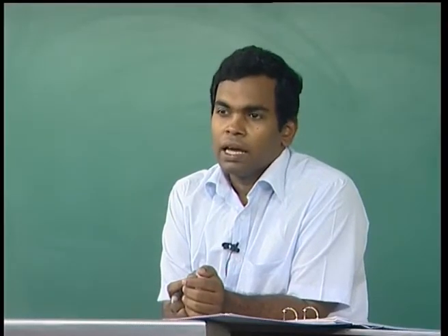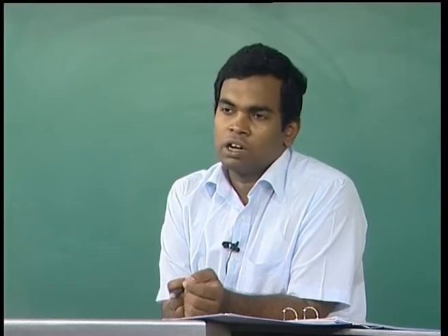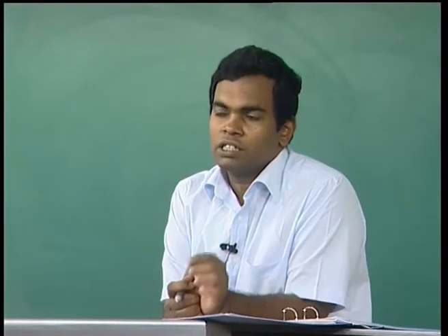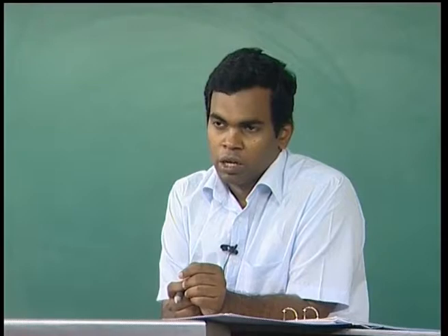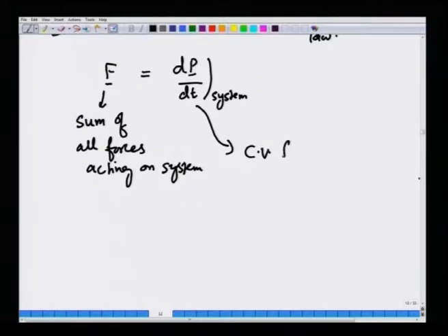We are not interested in following the same set of mass points in a fluid, because the fluid will come and go, but all we are interested in is whatever is happening in a control volume. For example, applications may involve a pump or a compressor or a turbine, in which case we are interested in calculating the power requirement for a pump. So, our CV will essentially involve the pump, and we are clearly not interested in following the same set of fluid masses, okay, as they flow through the pump. Okay. So, the Reynolds transport theorem is very critical in transforming this time derivative to the control volume framework.